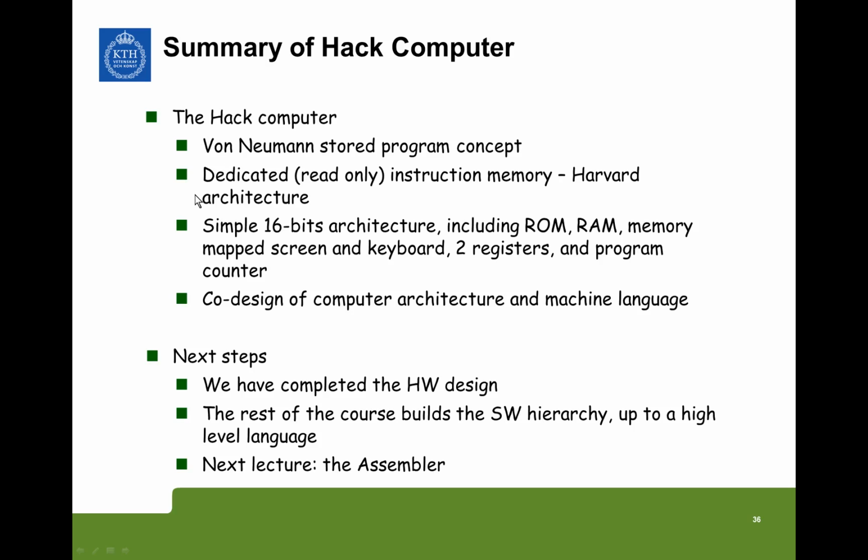We have seen that in our specific Hack architecture we have a dedicated instruction memory, which is actually not the original von Neumann architecture, but an architecture that's called the Harvard architecture. The computer we built is a 16-bit architecture, including a ROM, a RAM, memory mapped screen, keyboard, two registers, A register, D register, and the program counter. And we know that we have to co-design the computer architecture and the machine language.